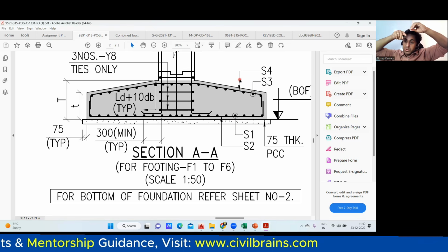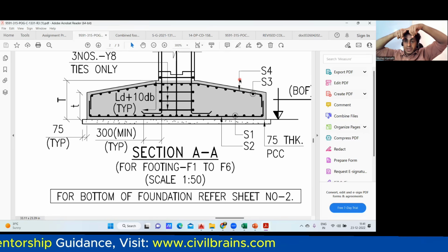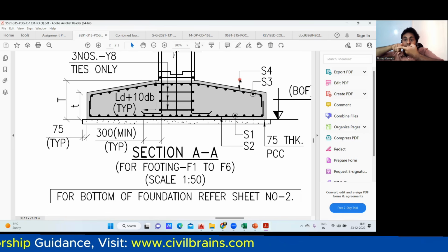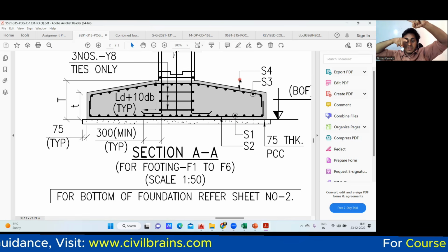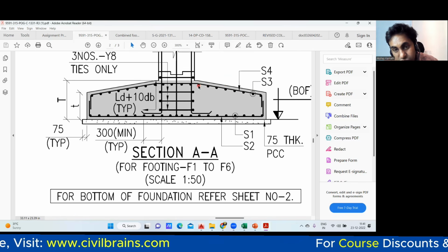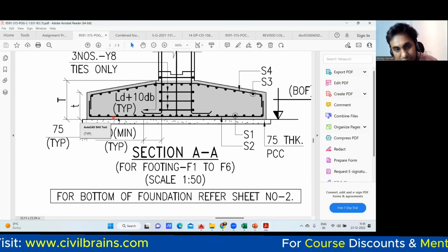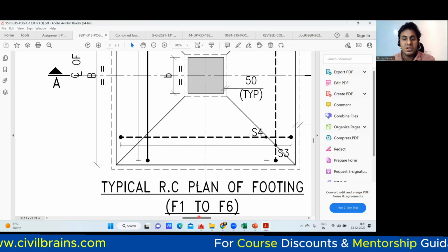This is the top main bar. This will be below that. But in the bottom, this will be main. Over that, the distribution will come. And in the top, this will be main. Below that, the distribution will come. Okay. So in the top, this will be my main reinforcement, and this will be my distribution. In the bottom, this will be my main reinforcement. The dotted is a distribution. Okay. Fine. And for that, they have given it here.